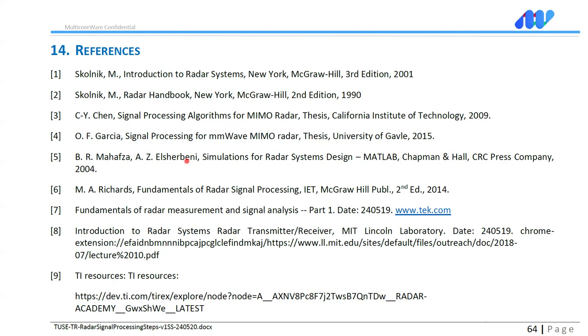I think that's a very good question, because it directly takes us to the optimization problem with the radar. Yes, if you take the pulse very long, you have a huge gain on the range correlator, because the wider it is, the match filter integrates more and more, which is going to carry a lot of energy.